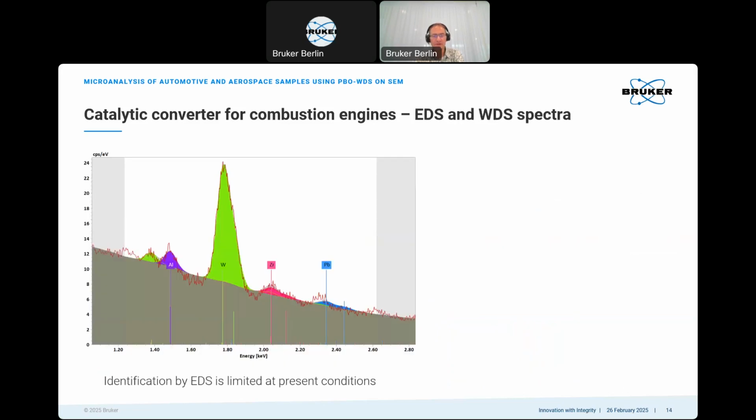Now the question is, is it really tungsten or is there more at this area? So we have the great tool of EDS deconvolution. The EDS is limited in spectral resolution, but has this tool of spectral deconvolution that helps in many cases to sort out the overlaps and well define the energies. Tungsten fits very well, but minor contents of silicon and tantalum may also be possible in this energy region. They're exactly at this position.